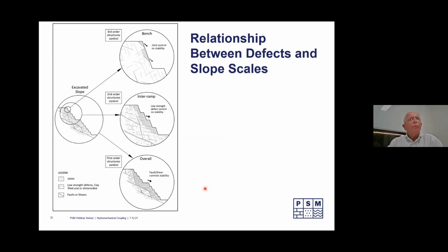The next thing is, as always in engineering, we must be able to place what we're doing in the concept of scale. So what we might be worried about on something that's 10 metres high might be the little cracks. We go to the next scale and we've got the next hierarchy of cracks that are important for that response until we get to the overall slope as shown here, and we're then looking at the big structures, the faults, the bedding, shears, those sorts of things. So placing the basic understanding into the slope scale or the excavation scale is also a fundamental step in this process.